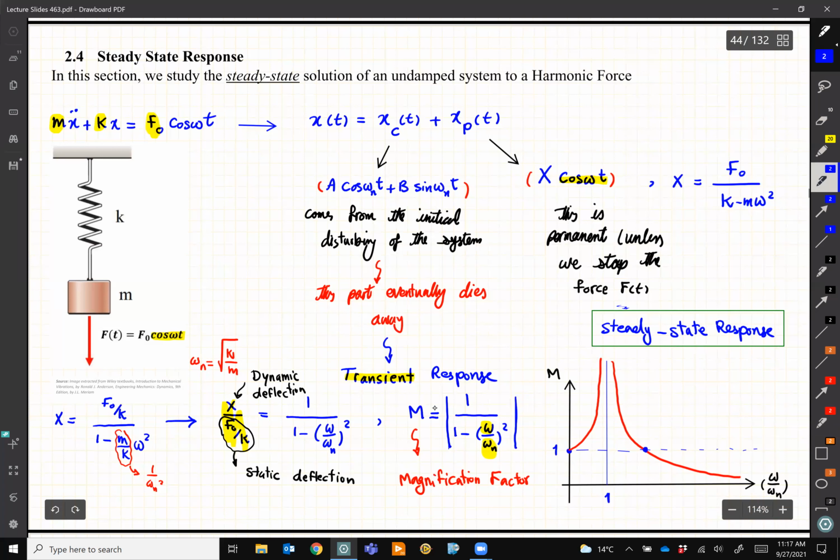So if I set this m equal to 1, because it's absolute value plus minus things, you will find out omega over omega n is a square root of 2. So this number, which is a critical value, is a square root of 2.